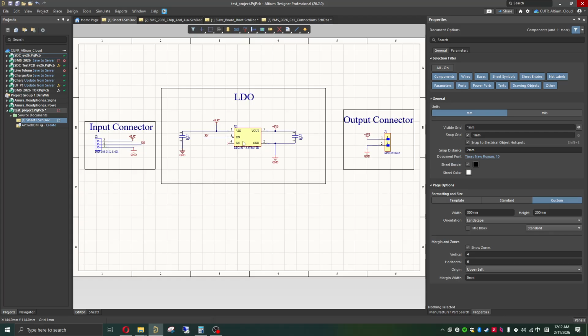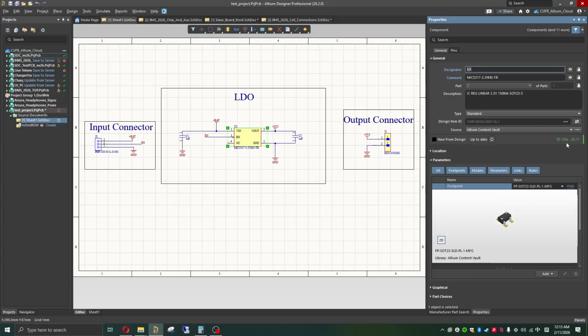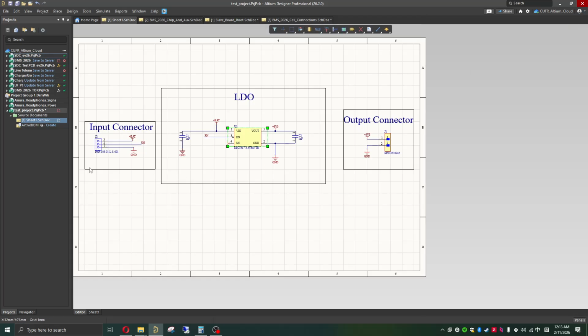through the manufacturer part search. If you're using custom components, it might be lacking a lot of information, but I'm not going to create it right now. But this is related to, for example, when I pick this particular component and it tells me what stuff is in stock. The active BOM is very useful on telling you what suppliers have access to this particular part, or whether they're running low on stock and what the prices are. And so you can even order directly from Altium if you really, really want to. But depending on the project and the scope, sometimes this is not a reasonable approach.